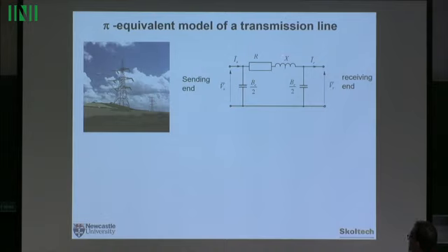Once again, this is a single-phase representation of a three-phase circuit. So this is a line, and this is the return wire, which in proper three-phase circuits is 0. But here, because we represent one phase, we have to provide a return. This is just for mathematical modeling purposes. So this is resistance and inductance.